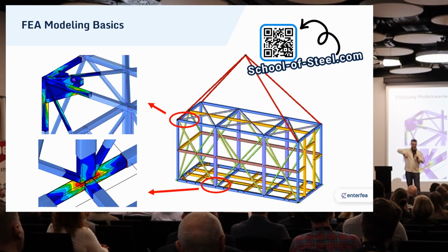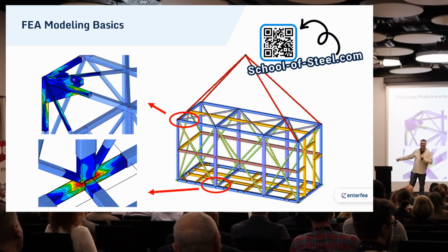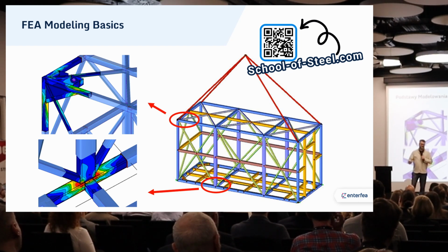This is where modeling a beam structure and simply cutting away a portion of it to create a plate model of a connection within the beam structure might be a much better choice. Then you don't have to worry about fake boundary conditions and you don't have to transfer anything manually because your model would calculate everything for you.